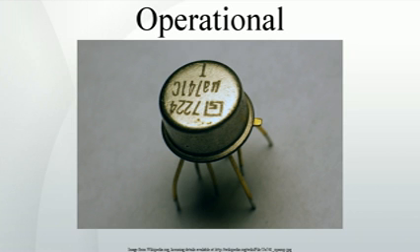When the desired closed-loop gain is high, op-amp frequency compensation is often not needed because the requisite open-loop gain is sufficiently low. Consequently, applications with high closed-loop gain can make use of op-amps with higher bandwidths, noise, distortion, and other effects. Reduced bandwidth also results in lower amounts of feedback at higher frequencies, producing higher distortion, noise, and output impedance, and also reduced output phase linearity as the frequency increases.